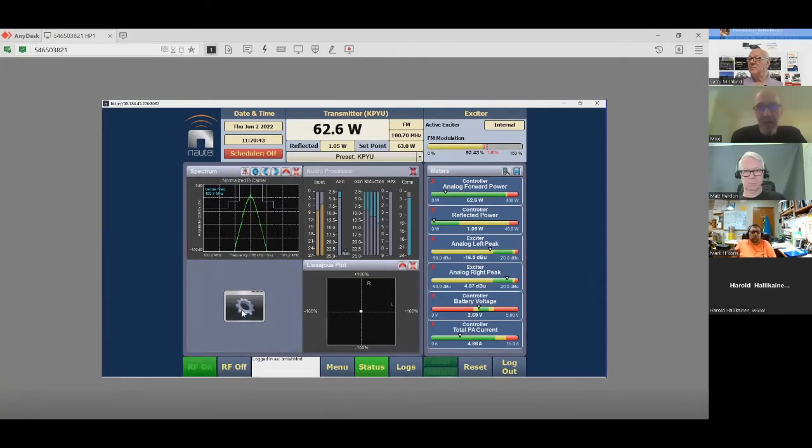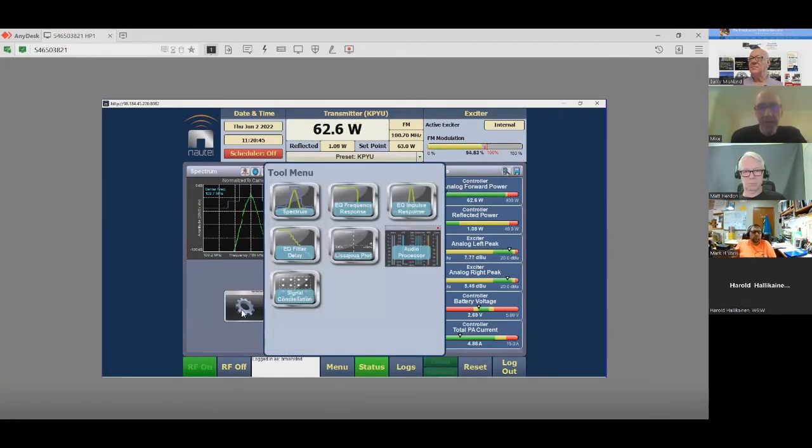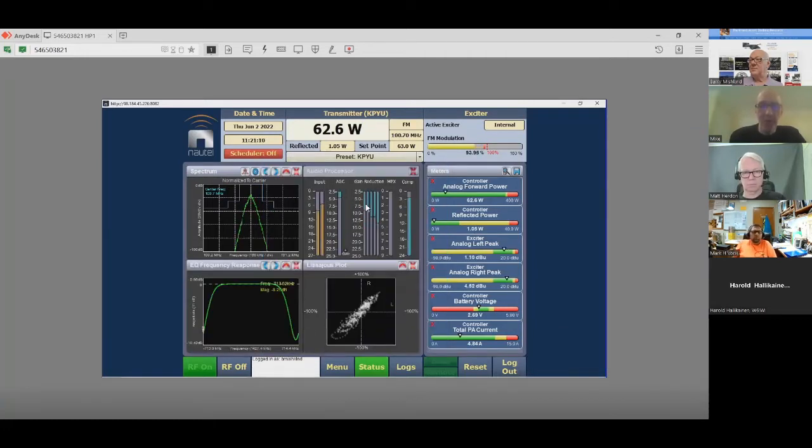And those widgets that you're referring to, which are three in total, there's the EQ frequency response, the impulse response, and the EQ filter delay. Those are all measuring the metrics of that filter. So it is a configurable item. It's something that we sell as an option. If it's not purchased, you're going to get the flat, or standard, filter, which is just a bandpass with very broad skirts. It allows the signal to pass without any problem.